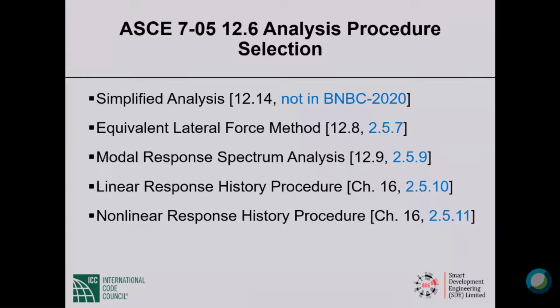Equivalent lateral force method, section 12.8 of ASCE 7-05, your section 2.5.7. Modal response spectrum analysis, 12.9 of ASCE 7, BNBC 2.5.9. Linear response history analysis, chapter 16 of ASCE 7, 2.5.10 of BNBC.